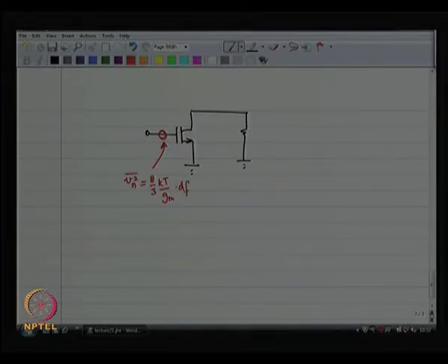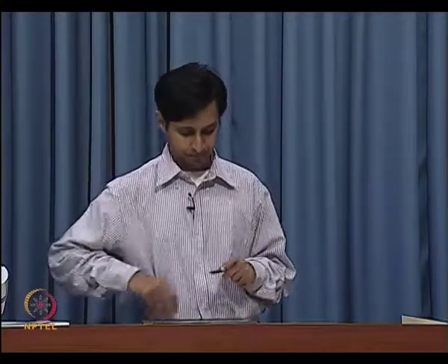Now, this particular noise voltage has nothing to do with the gate noise. I need you to understand that. This particular noise voltage is modeling the noise current in the channel. It has nothing whatsoever to do with noise which appears on the gate because of gate resistance, nothing. Okay, that is a separate phenomenon. If you want to take account of it, you have to add it in further, right. It is uncorrelated with that. Okay. So, with that understanding we proceed.